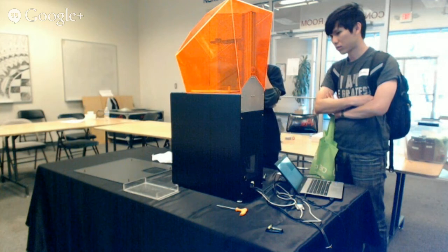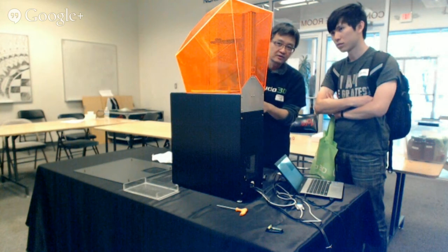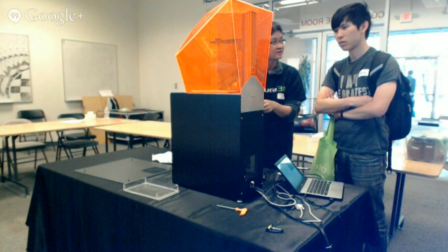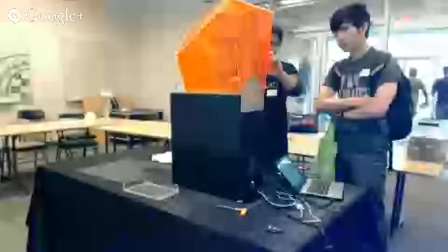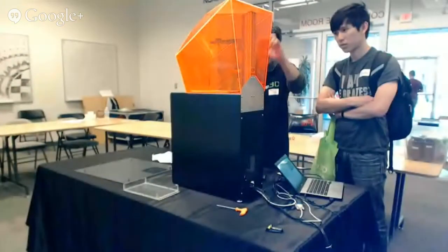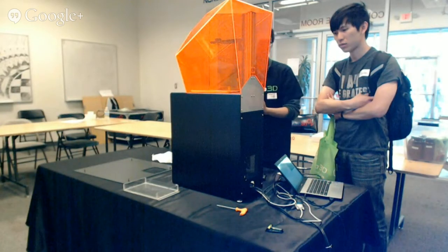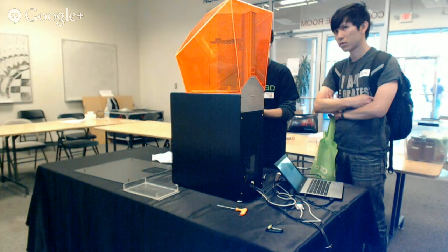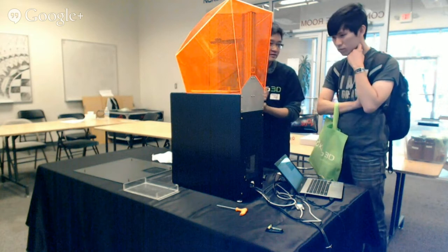Okay. Yeah. I mean, Creation Workshop has a way to build a base layer. It will try to figure out what the dimensions of the part are and then go out a little bit. And then it builds like a millimeter thick, which is way too thick. It actually makes the layer less effective to be so thick, and then you have to dial it back down. I don't do that anymore. I just go into Paint. Yeah, I use a single layer, and I'll go into MS Paint, and I'll just make a big white rectangle on that first layer, and that's it.